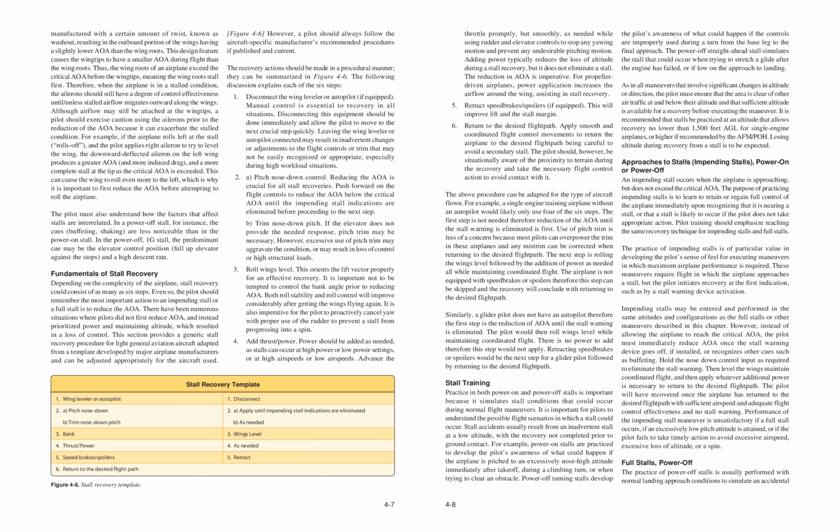4. Add thrust/power. Power should be added as needed, as stalls can occur at high power or low power settings, or at high airspeeds or low airspeeds.